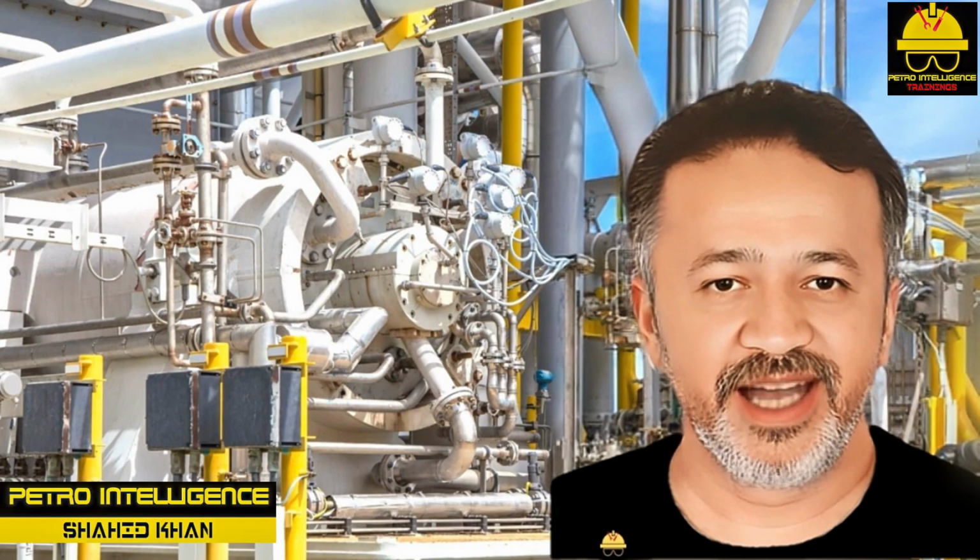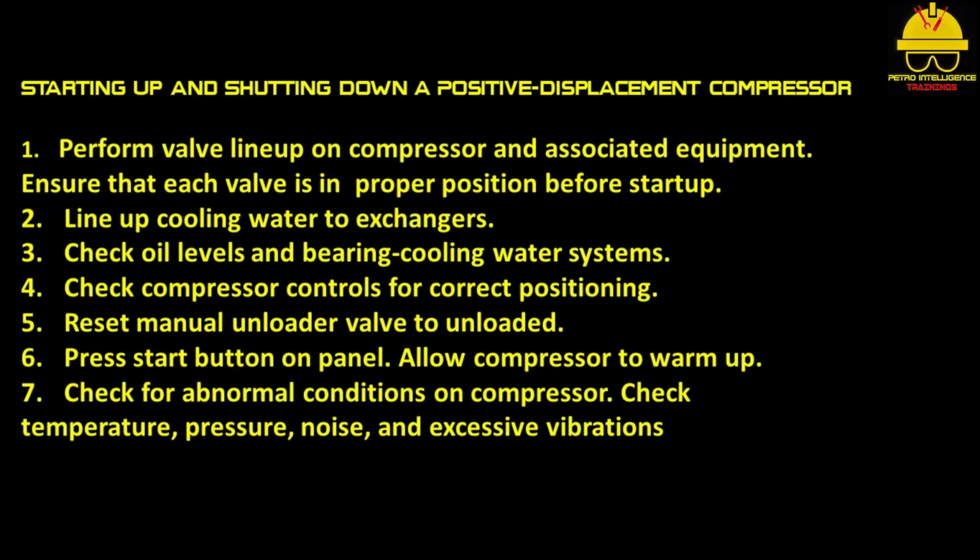Starting up and shutting down a positive displacement compressor. 1. Perform valve lineup on compressor and associated equipment. Ensure that each valve is in proper position before startup. 2. Line up cooling water to exchangers. 3. Check oil levels and bearing cooling water systems. 4. Check compressor controls for correct positioning.